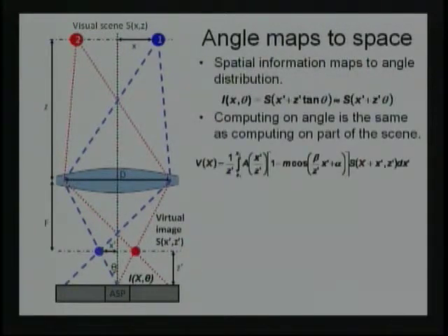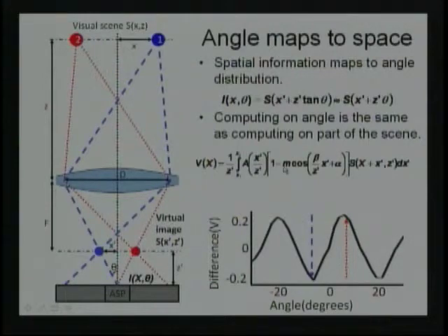So we can formalize that math, and it's basically a convolution integral. But what you want to see is that in here we have the angular response of our pixels, and it's basically responding to x, the location of the image, and z, the offset of the image in the third dimension. So both of those things are contained in that response. And what that means is that our response is combining the blue light coming in at this point on its angular response and the red light coming in at this angular response. Basically it's just convolving the spatial locations by its angular transfer function modified by depth.